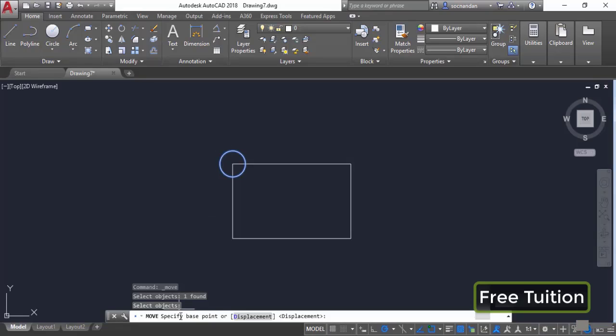As you can see here, the command line prompts you to specify the base point. So the base point will be the point from where the object will be picked. Now click here and you'll notice that the object will now move along with our cursor. Now look at the command line and it now prompts you to specify the second point. So the second point will be the destination point where you want to move it, and click there to move the object. So that's quite simple.